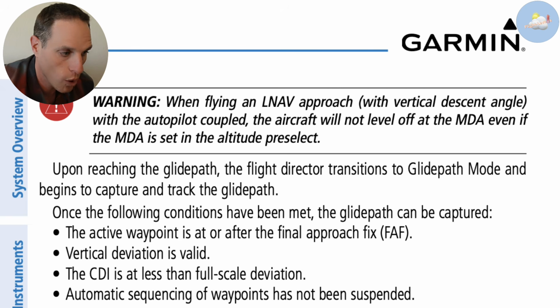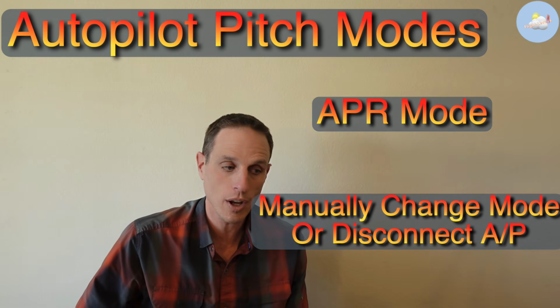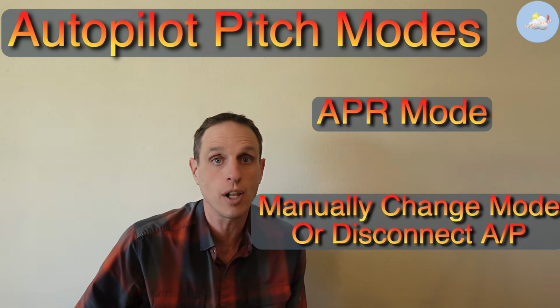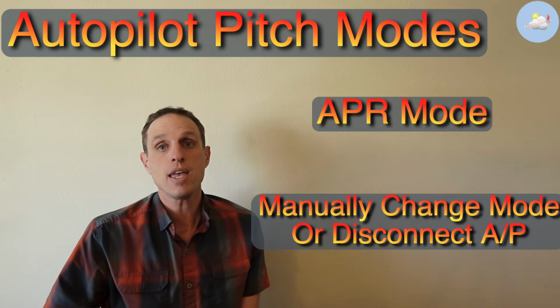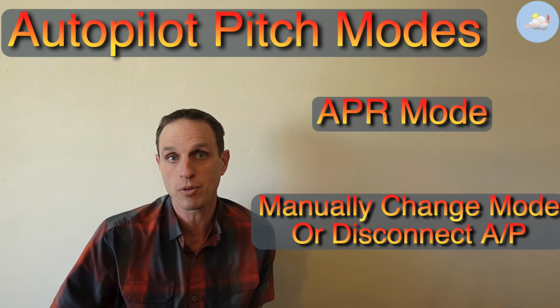In another place: warning, when flying an LNAV approach with vertical descent angle with the autopilot coupled, the aircraft will not level off at the MDA even if the MDA is set in the altitude pre-select. Just like we've talked about, autopilot will continue following a glide slope indefinitely until you manually switch pitch modes.